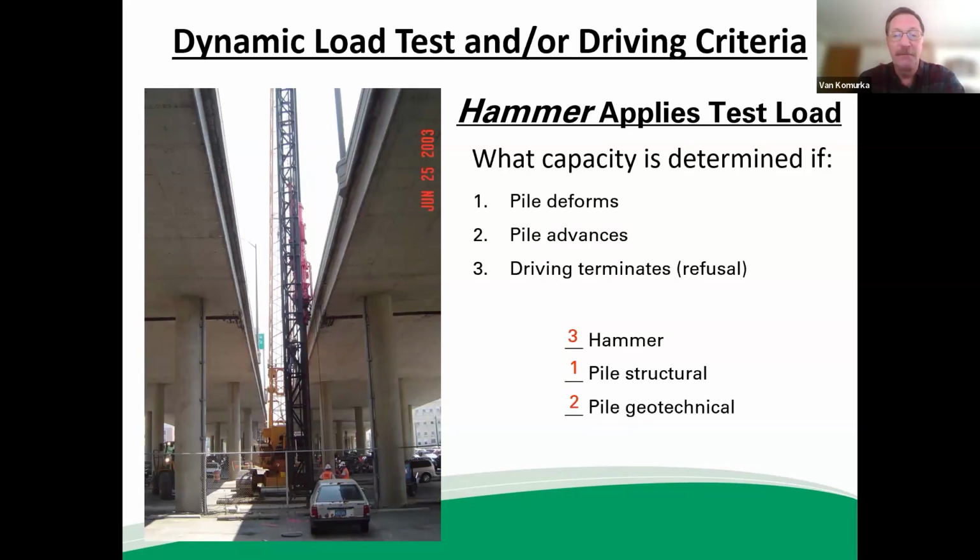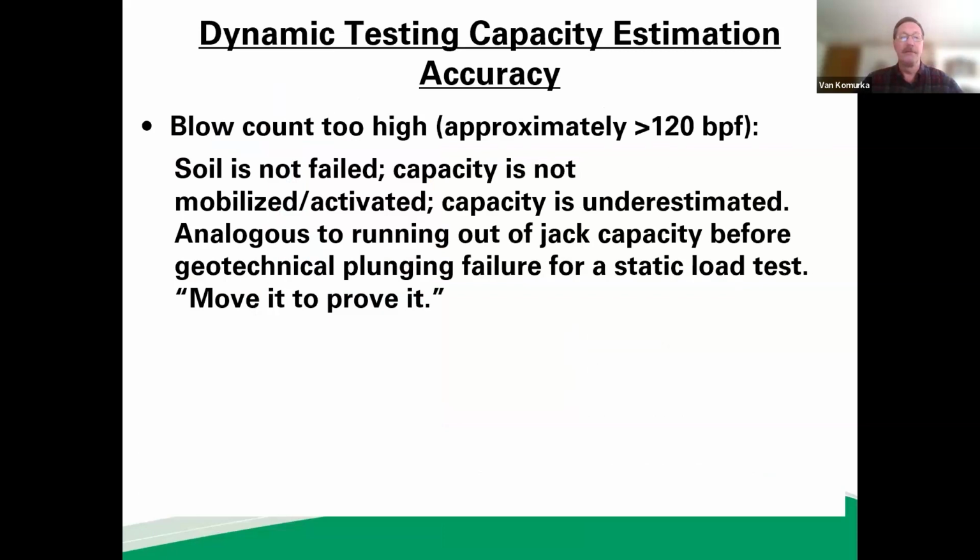Therefore, what you're determining at practical refusal is the hammer's capacity or its transferred impact force. But what you're learning about at practical refusal isn't the pile's geotechnical capacity. At practical refusal, you're learning about the hammer's capacity. So keep that in mind as we go forward.